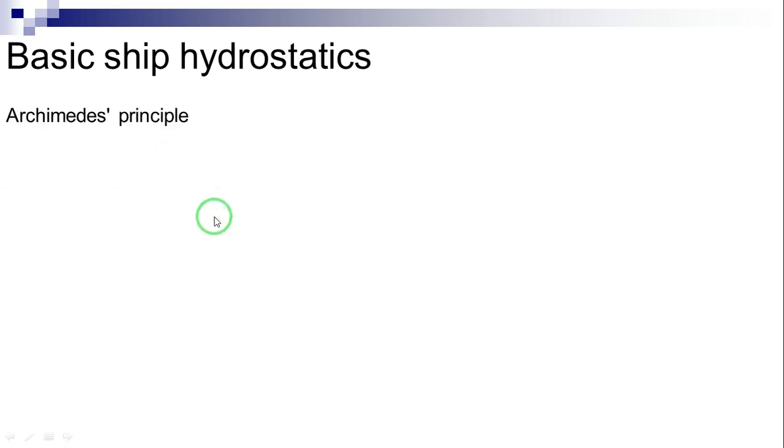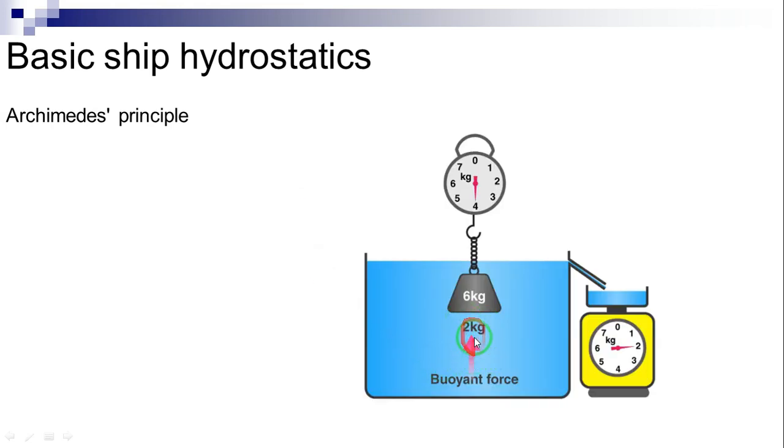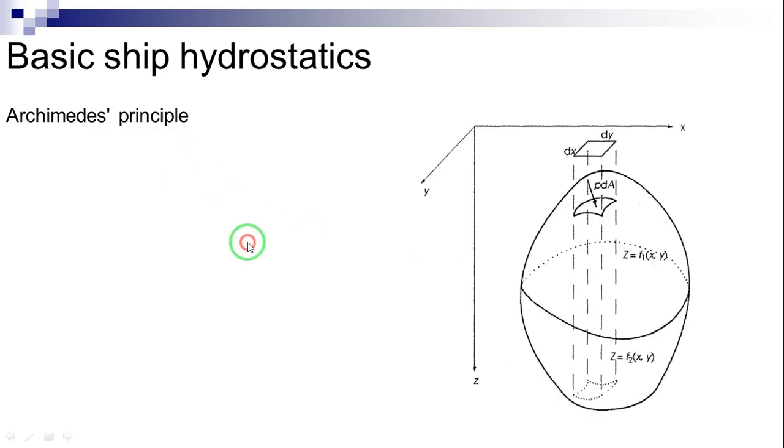Archimedes' principle. A body immersed in a fluid is subjected to an upward force equal to the weight of the fluid displaced. The above statement is known as Archimedes' principle. This force, which is referred to as buoyancy force, is applied in the center of the displaced volume, the submerged volume. The Archimedes principle can be demonstrated for a general submerged body as shown in this figure.